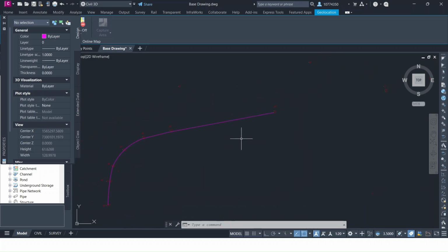Once you do a lot of this, you can just straight up set all the elevations to 0 when you join it together. But for right now, we're going to make sure everything has an elevation based upon the survey points. So when we hop into making our existing surface, it makes things a little bit easier. But for the most part, you can have all these set to an elevation of 0 if you truly desire.